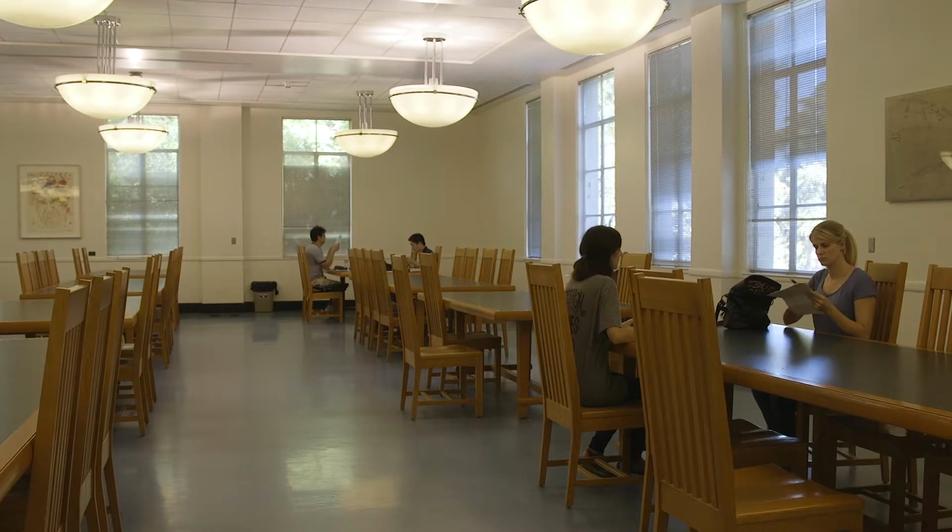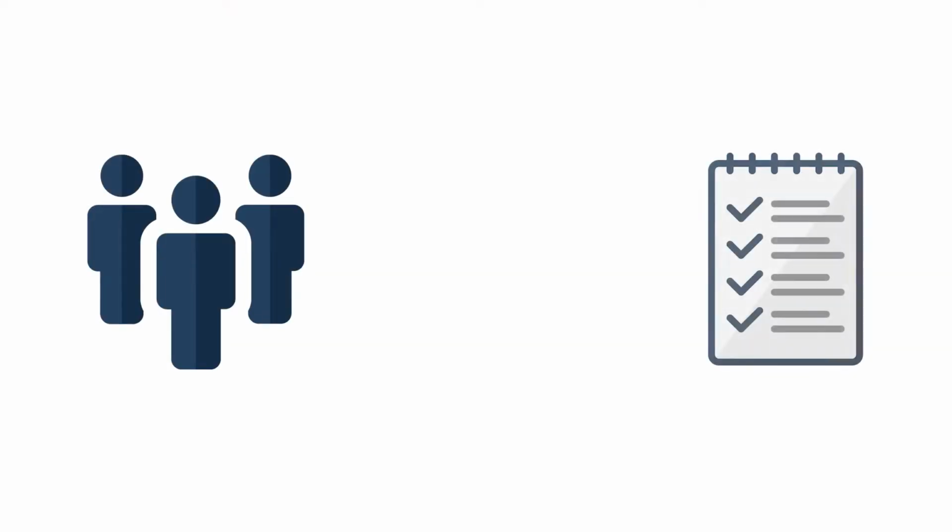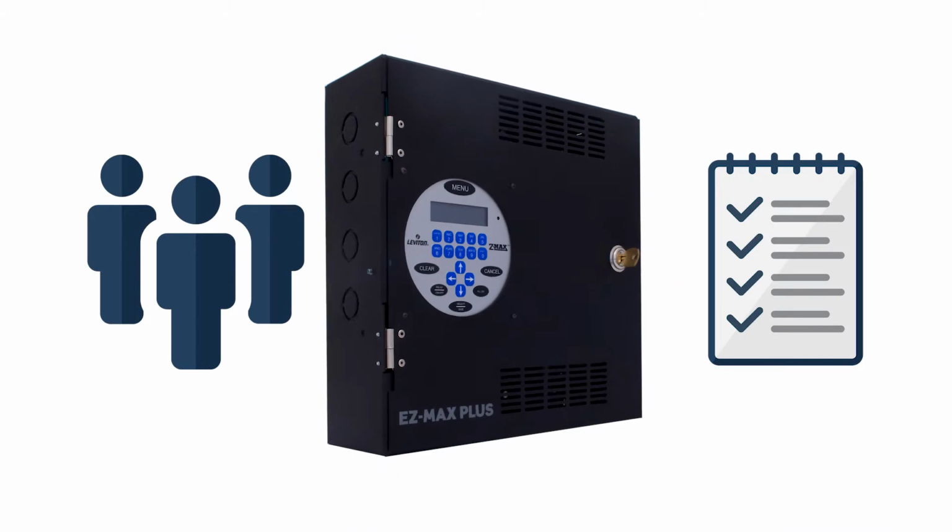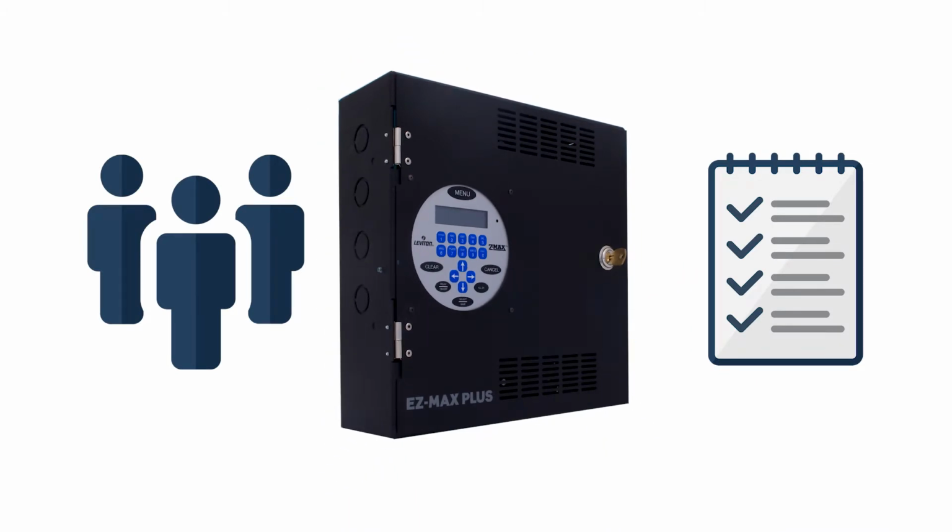Multi-level controls enable buildings to schedule light levels based on occupancy or task. When multi-level controls are installed and available, a programmable time clock, for example, can be used to reduce lighting in the evening and early morning when building occupancy is low.